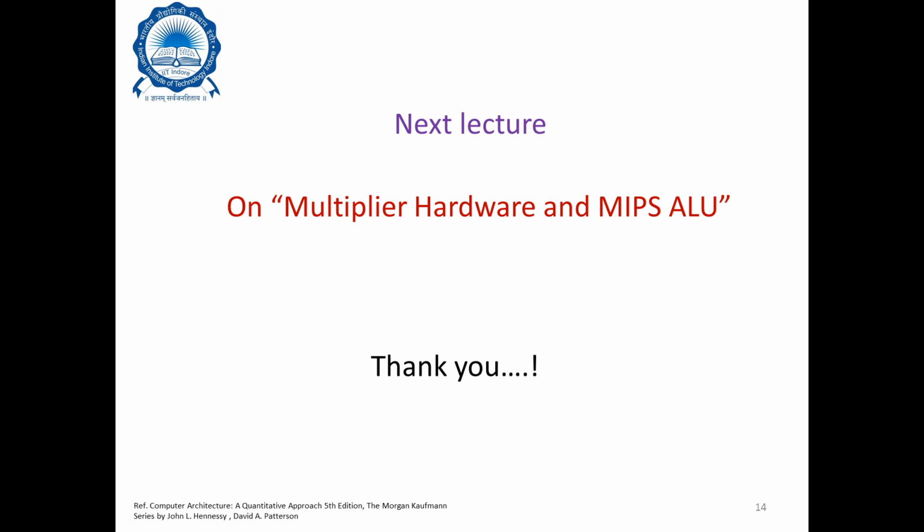Okay, so in this lecture, you've learned a lot of things. You've learned so many different complex examples of MIPS. You've learned about pseudo instructions. You've learned about how to load a 32-bit constant using LUI ORI. You've also learned about how we can break pseudo instructions into multiple internal MIPS instructions, which is understandable by MIPS processor. And you also understood about how to compute the target address for jump, target address for branching. You also understood how the way to convert a target label to a target address is possible for jumping and branching both.